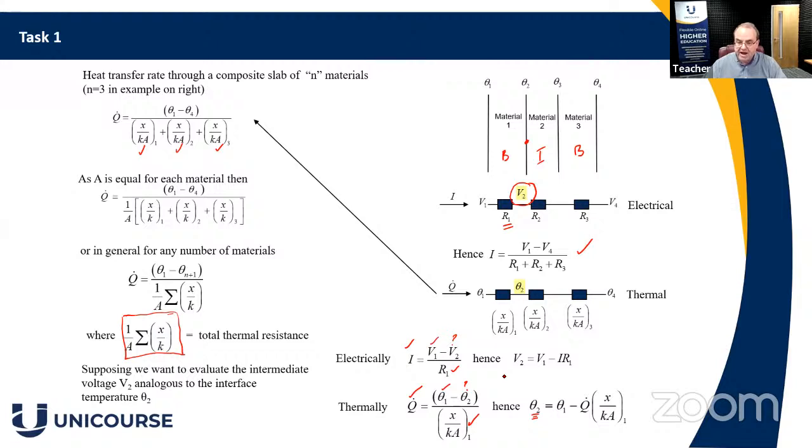Right, there's one more term that we've got to add to this expression. We've looked at conduction through those slabs. Now we've got to look at convection away from the outer surface. So it's all well and good that we're saying we've got heat flow through that system. Draw this Q. But there's two mechanisms. The heat transfer will be by conduction through the material, so conduction there, conduction there, and conduction to the final material. But away from the surfaces, you have convection taking place.